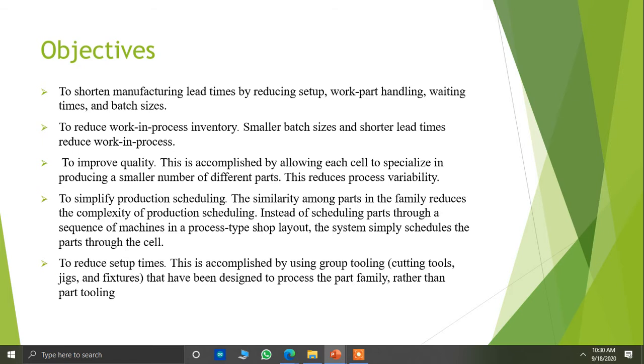Apart from that, you have reduced setup times. All these typical cell layouts will reduce setup times, because for starting up the process, setup time will be very, very nominal. You have the raw material very well processed and it can be fed into the machines, so the production process continues. So how can this be achieved?